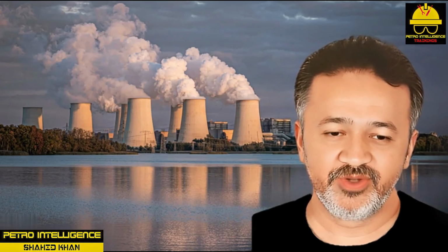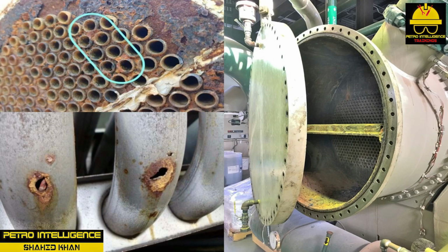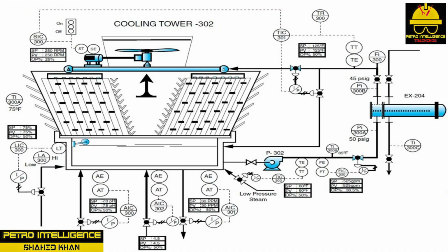Ruptured heat exchanger tubes. If the tube ruptures on X2O4, the butane, pentane, and catalyst mix will pour into the recirculation water since it is at 100 psig and the recirculation water is at 45 to 50 psig. The pH of the cooling tower water would also become very alkaline and set off the high pH alarm.